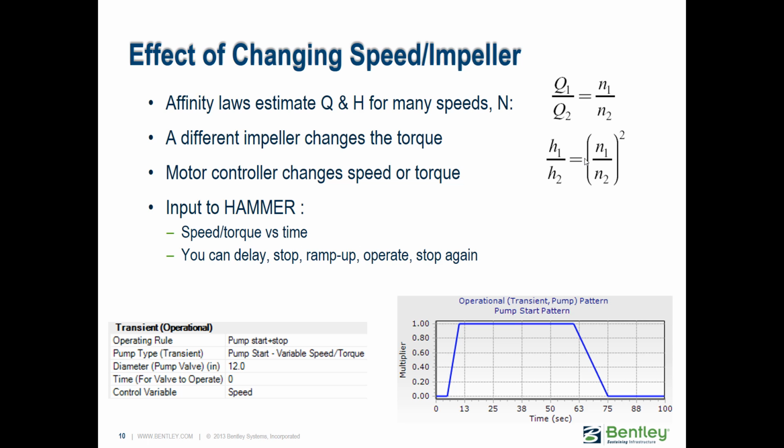So you either need to control it by speed and assess and implement the actual delay that it would take for that impeller to actually reach full speed, implement that into the pattern there, or choose the control variable as torque, and that way you can say instantly 0 to 1 within a fraction of a second, and that's like flipping the switch.